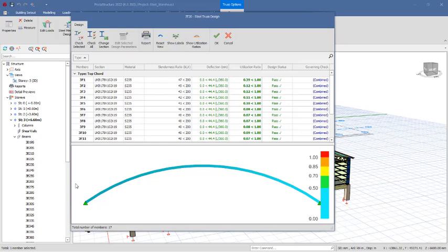Okay, so this curve beam consists of various members, split into fragments. You can see it over here, and the material sections use the smallest section's strength, the smallest steel strength right there. Over here you can see the slenderness ratios. The highest slenderness ratio we have here is 42, less than 200.